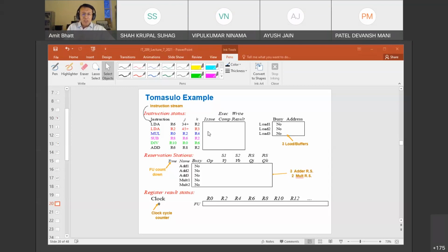So here, I want to step back and again stress a point that your simple ALU can also do matrix multiplication. There is nothing against it, right? On your ARM7, you can write a program for matrix multiplication. It does not have a MAC pipeline, or a dedicated DSP, or a dedicated GPU. So it can do matrix multiplication on its own on a given ALU. It's a very simple inline processor.